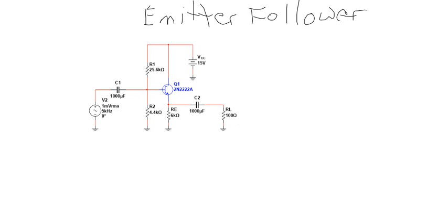I don't remember which one they call it in the book, since they were using little RL in the common emitter circuit. We'll go ahead and use little RL for this. And that's RE. And again, for AC, remember the capacitor is going to be a short, so those two are in parallel.